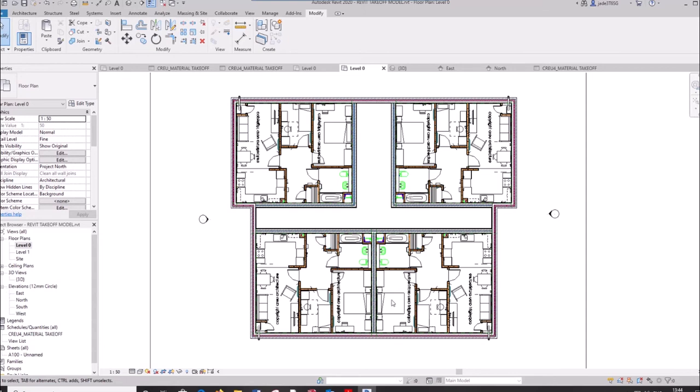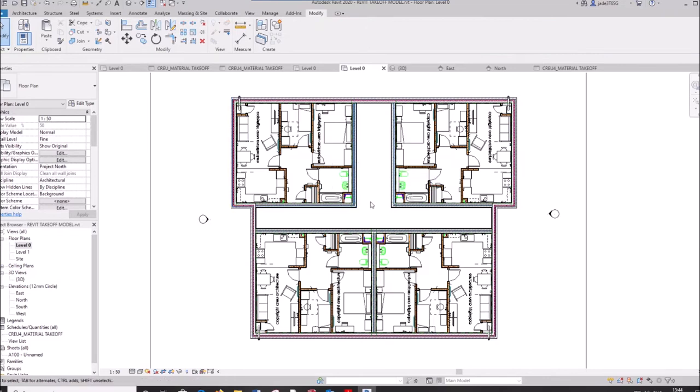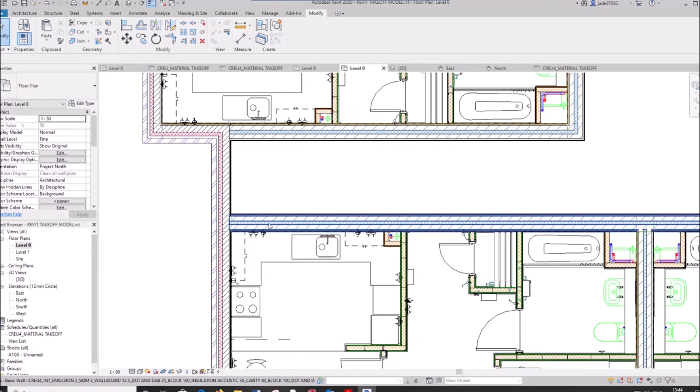So using the standard apartment layouts, we've created a notional apartment block. We've got an entrance corridor here, with a corridor down here, possibly with a staircase up to the first floor. Party walls are masonry with quilt insulation fill. External walls are blockwork, insulation, cavity and brickwork.